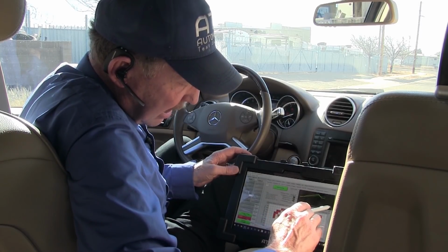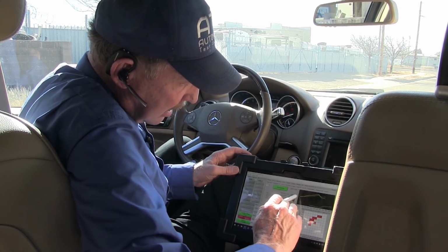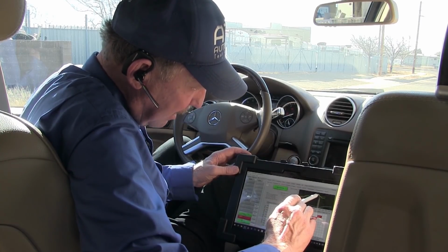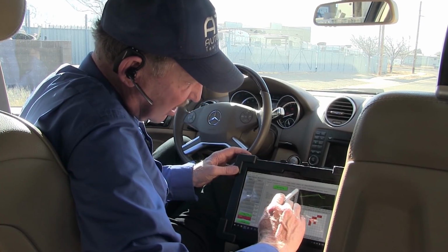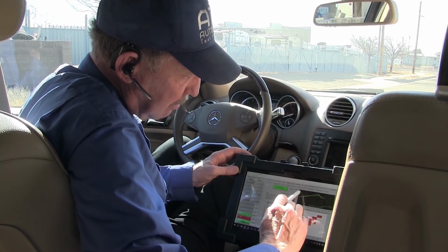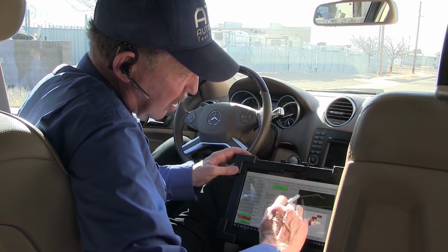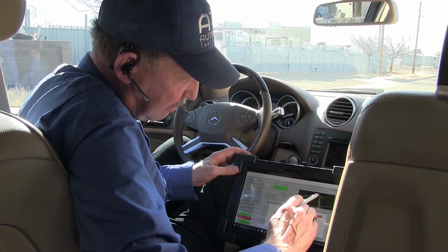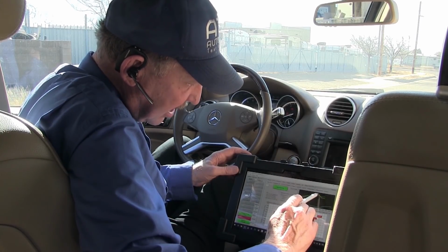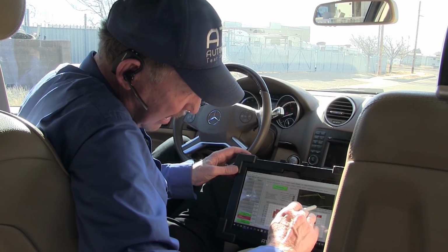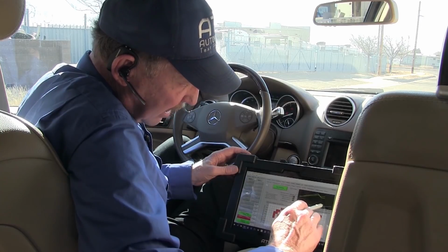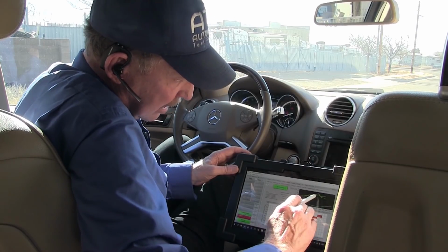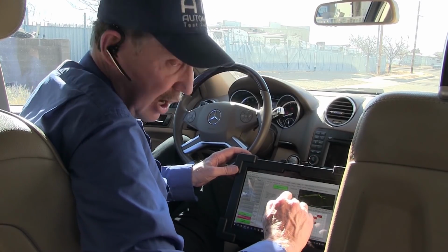This blue one is the air reading, and you see how it's pretty flat? Do you see how we're going from 20% to holy 60% trim adds up here? And that's more than most cars will give. 50, 60% trim is as much as I've seen. You don't get much more trim than that. So this is not an even curve. You can see that I went from 20 to 60% trim. And do you see how flat my line is for air? Well, if the air is the problem, it's going to have to match this curve up here, and it doesn't. It's all flat. So this tells me right now that this is not on the air side.